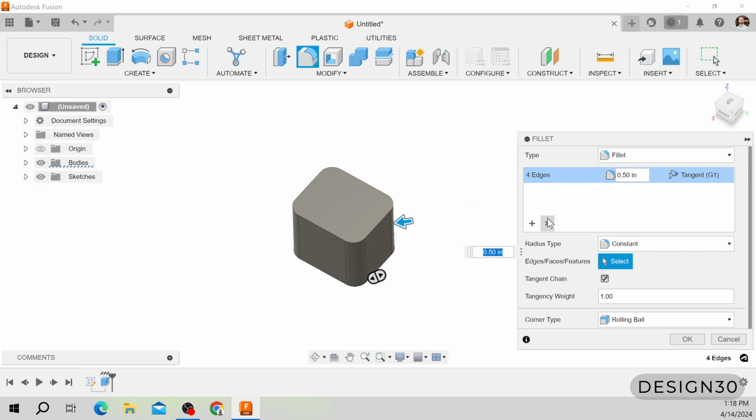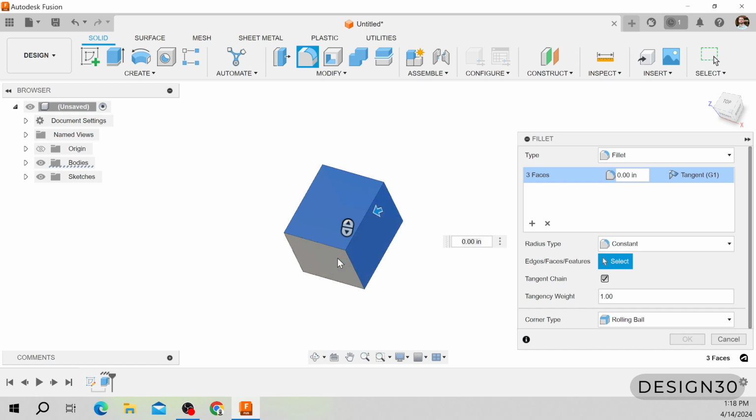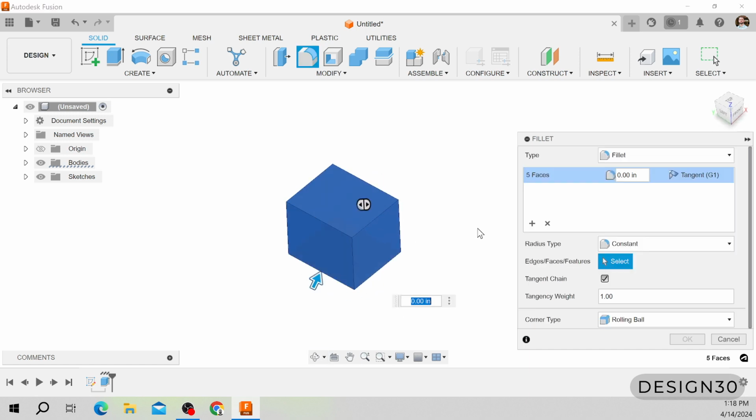Again, if we go back to selecting faces, and you can select multiple of these, you'll also see that your selection set is these faces. Then you can specify your radius here. Whoops, I added an extra period there. Let's go 1/4 inch, and boom, you got those.